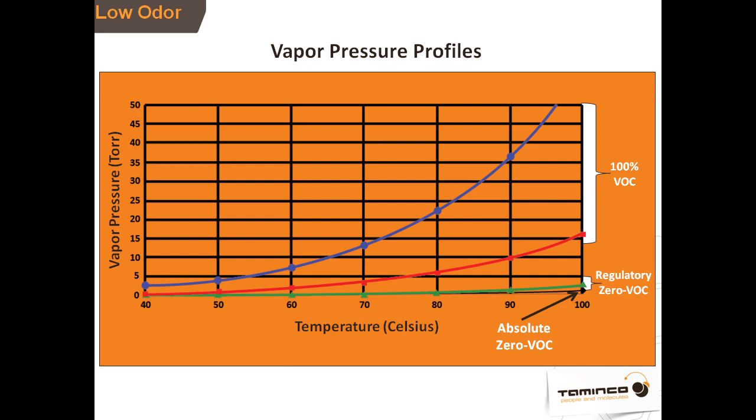Now, that's a much higher molecular weight. It has poor neutralization efficiency. You'll generally have to use 2 to 3 times as much as you would ammonia or a more hydrophilic, lower molecular weight amine. But you do gain all the multifunctional benefits. So in some cases, you can replace other additives like the coalescing solvent, some of your pigment dispersant, some of your emulsifier, and end up with a cost-equivalent formulation that has zero odor and a very low level, at least a very low level of VOC. We're hoping that it's going to be categorized as a zero VOC, but that development is still ongoing. There's nothing which is officially a zero VOC or a VOC yet.